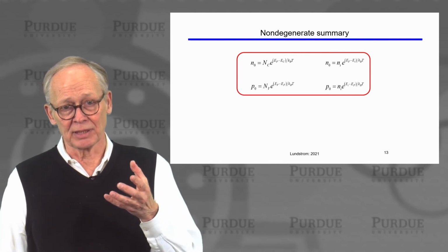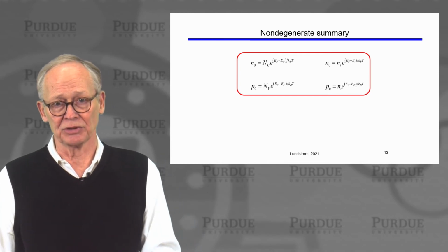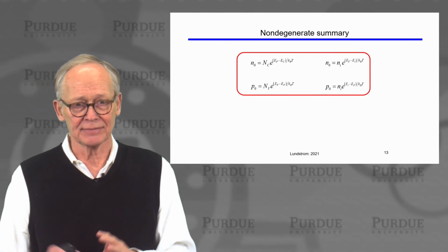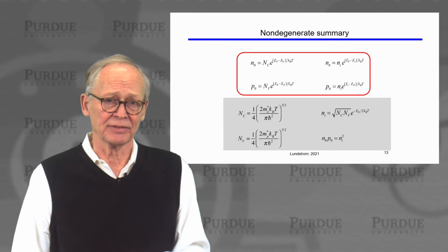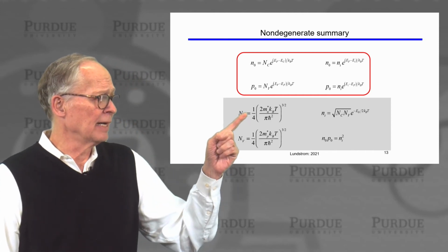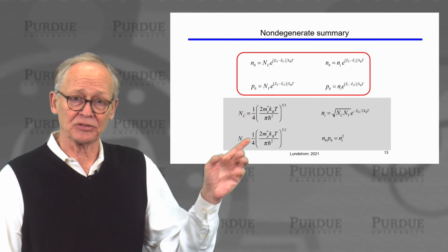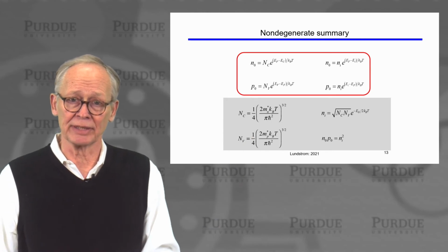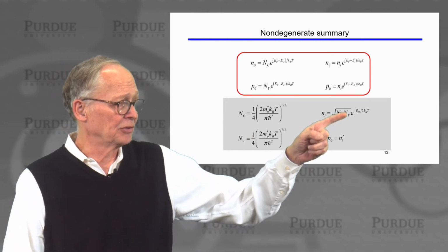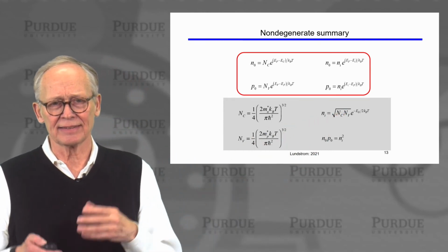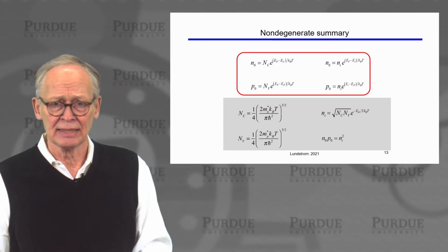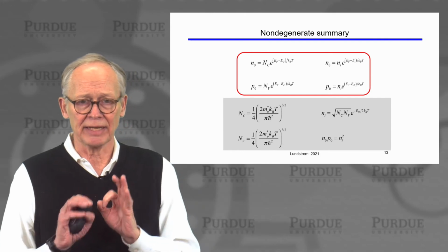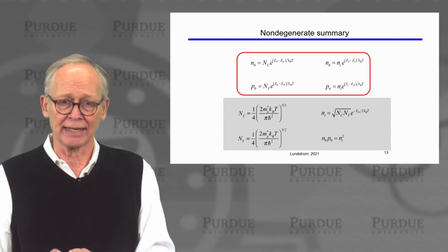Is the Fermi level above or below the intrinsic level? These are mathematically equivalent and identical. We'll use the one that is most convenient for us. We have these effective densities of states, which we'll need whenever we're doing a calculation. We have this expression for the intrinsic carrier density, which gives us an understanding of how it varies with band gap and temperature. And remember, in equilibrium, n times p is always ni squared.